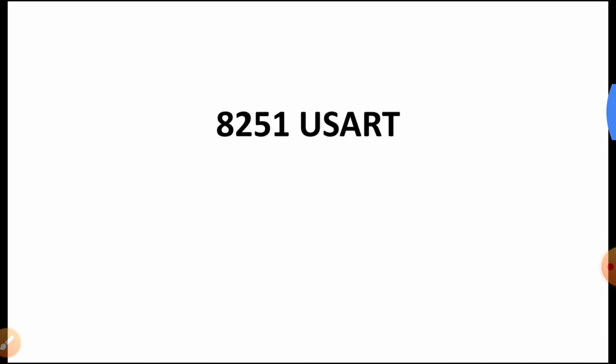So, if we want to transfer the data over a long distance with the help of parallel communication, it is not economical since it increases the cost of the cabling, and it is impractical too because there are many devices which do not accept parallel data, for example a CRT terminal.